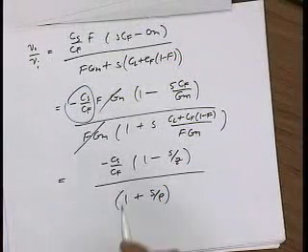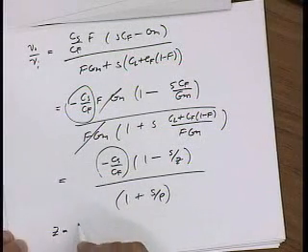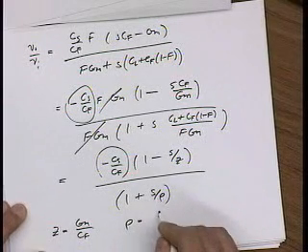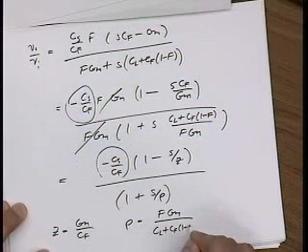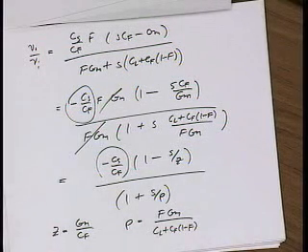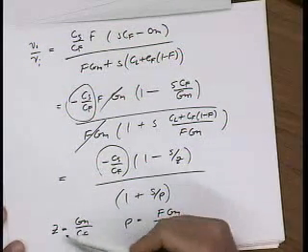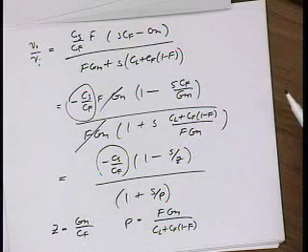Now this equation is clean, and I write that my zero is GM over CF, and my pole is FGM over (CL plus CF)(1 minus F). So then I look at my pole and zero and say, do these make sense? Does it make sense that at a frequency GM over CF I'd have a zero? You check your answer. In this case it's so simple that you can check it, to make sure you didn't make any algebraic errors.